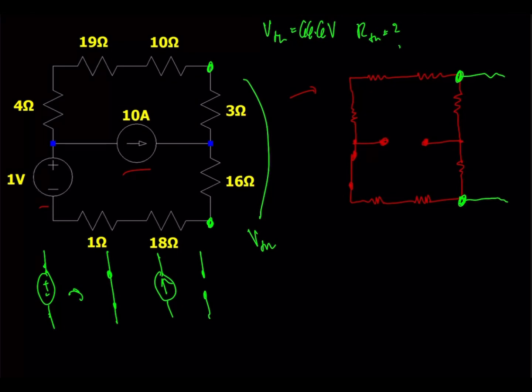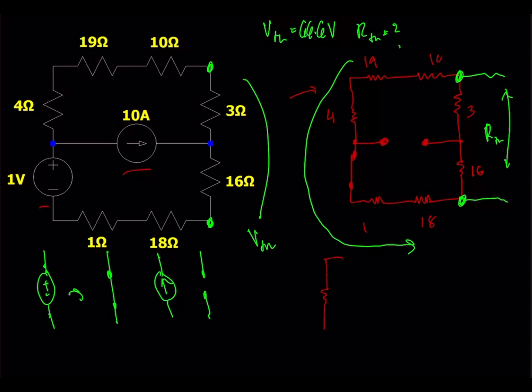So we can bring back these resistance values here. And again, we're trying to find the equivalent resistance as seen from these terminals. And that's our Thevenin. So if we look closer, we can see that these resistors are all in series in this outer branch. So that can simplify to a single resistance, which is just their sum. And that'll end up being 52 ohms.